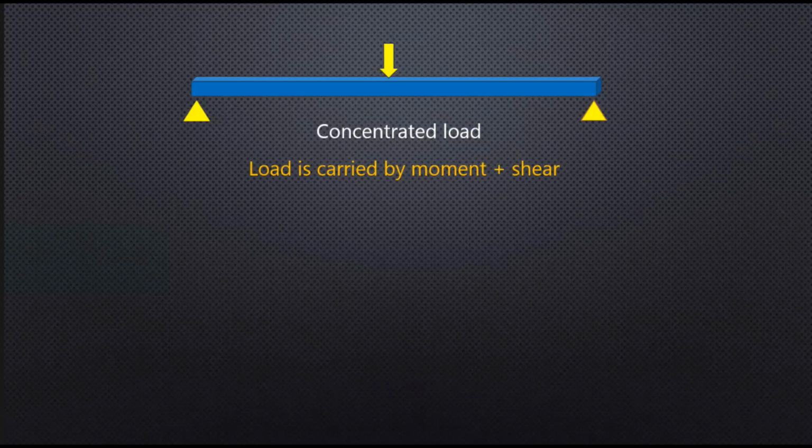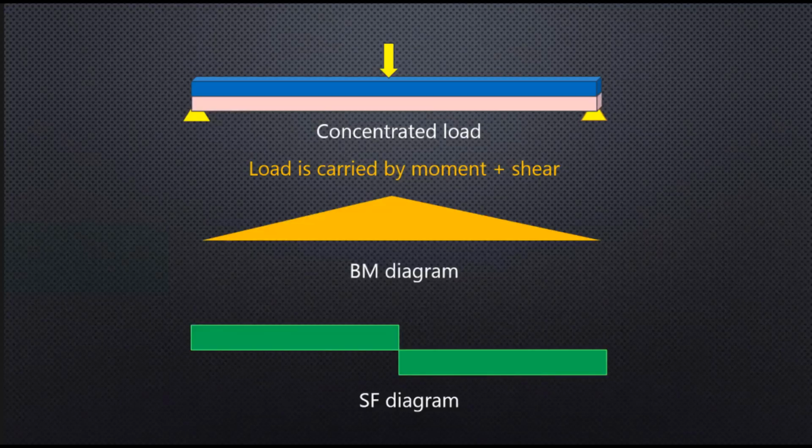I have already told you in the last lecture, it is because of the shear rigidity that moment comes in structural systems. Now, this is the bending moment diagram. I wouldn't say one sign, but the entire curvature is cup-shaped bending. Of course, the bending moment should be drawn on the tension side. That's fine. Leave it.